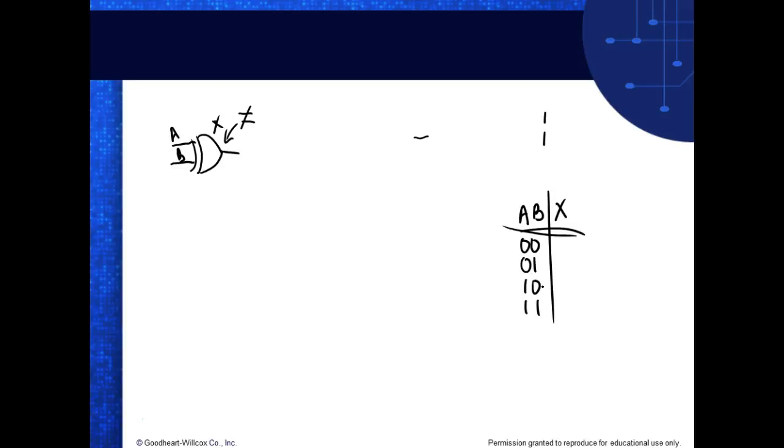But what I'm dealing with here, I'm still only dealing with two bits. So what would we get here? If they're not equal, we get a high. Okay. So this would give me my truth table. They're not equal here. They are equal here. They're not equal there. They're not equal here. They are equal here. So here the output would be energized, and here the output would be de-energized, which would be the same thing in both. But I'm still only doing this with two bits.